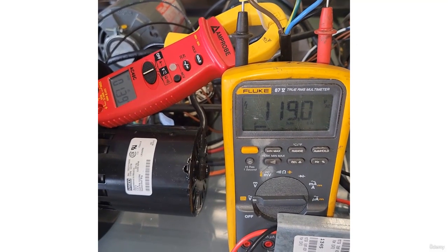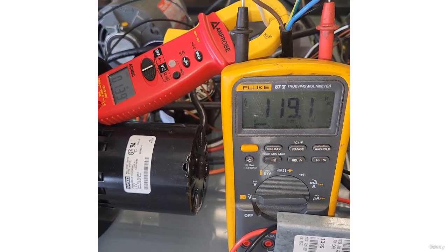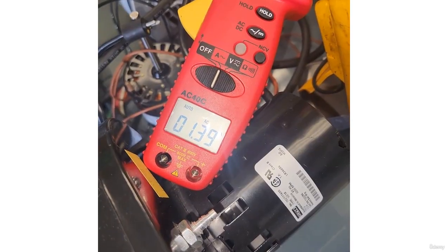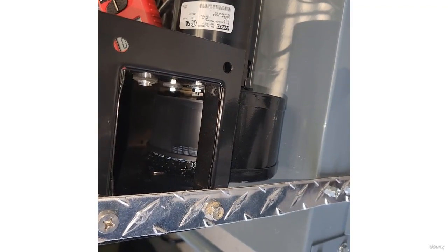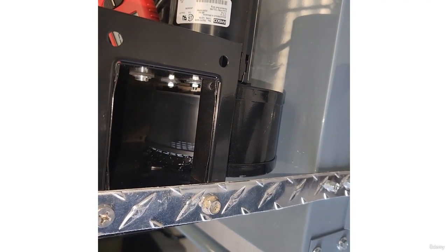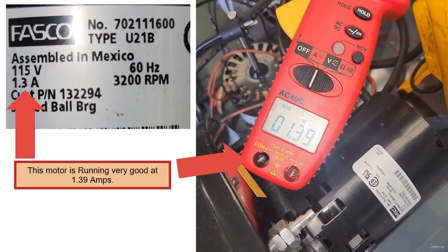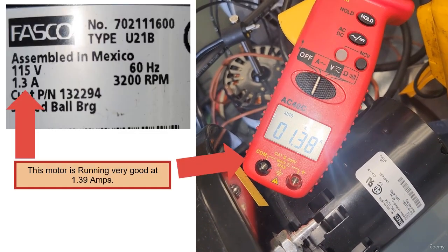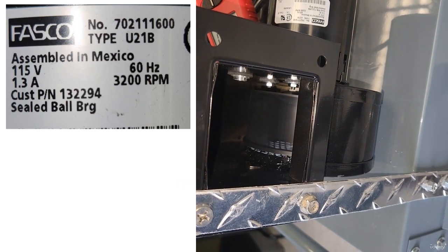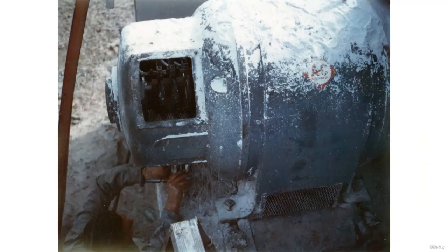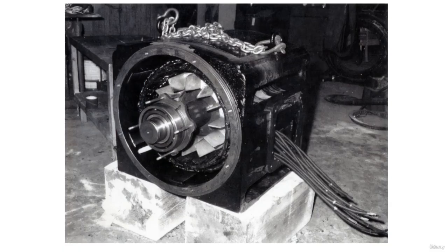Check the incoming voltage to ensure it is correct. At the correct voltage, what is the amperage? Is it within 10% of the rated amperage while it's under load, doing the work it is supposed to do? If it's not, then you have to determine why. Is there another factor other than the motor itself causing high amps, like an improperly adjusted pulley, wrong fan blade, blocked air path, or bad bearings on the component it's turning?